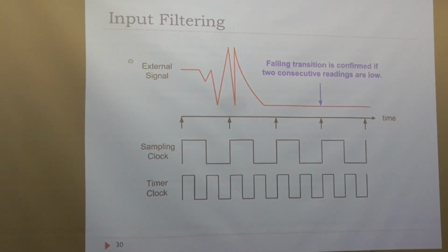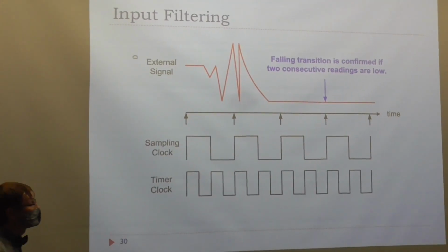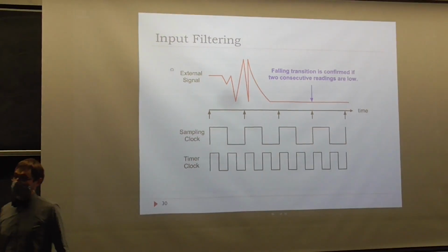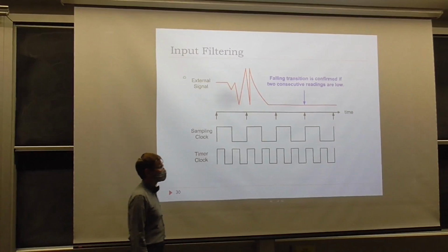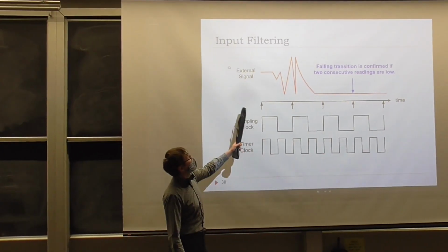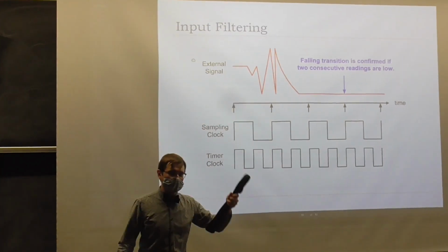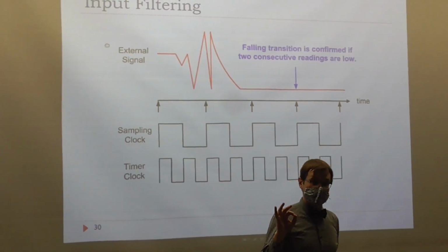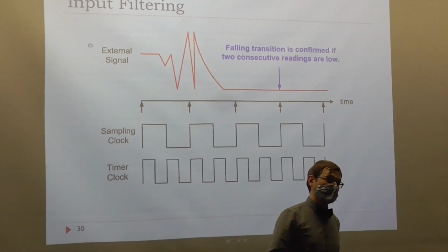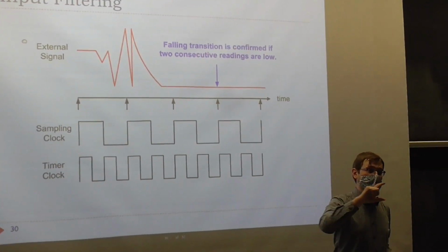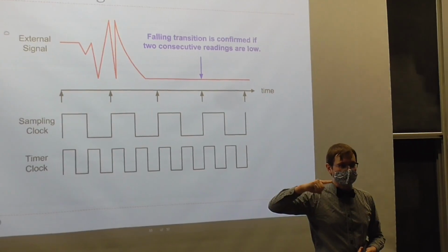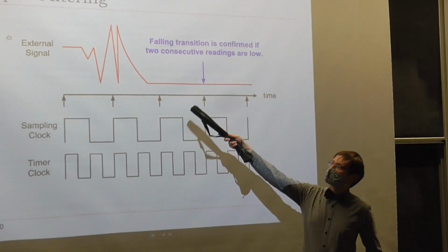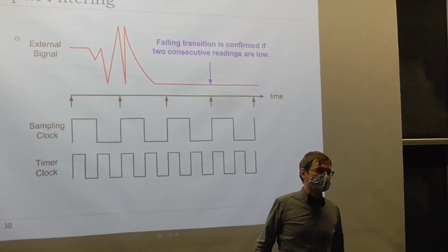One little point further, and then we'll talk about an application of this. One of the things you have to worry about is how clean your signal is. You should probably not assume that your signal is that clean. It depends on what you're measuring. For example, going back to the last set of lecture slides, if you consider what the input from a push button looks like, you do have that mechanical bouncing, right? Which means you're going to get a signal that pops up and down a little bit until it reaches a rest state. So this is what this jaggedy part is meant to model.